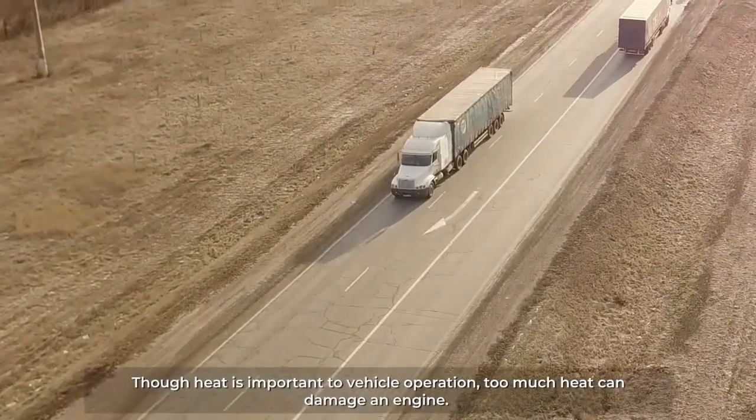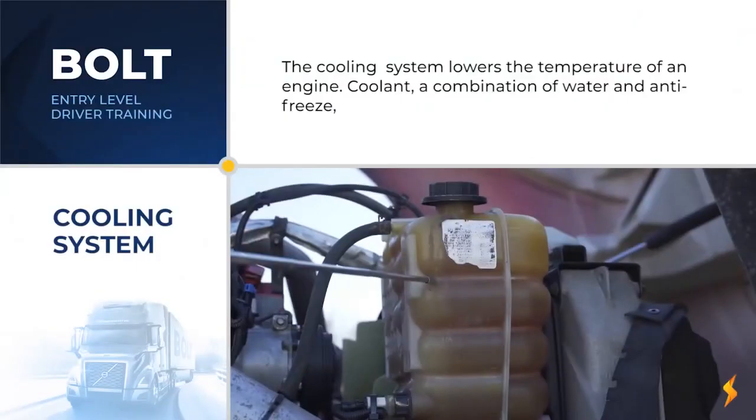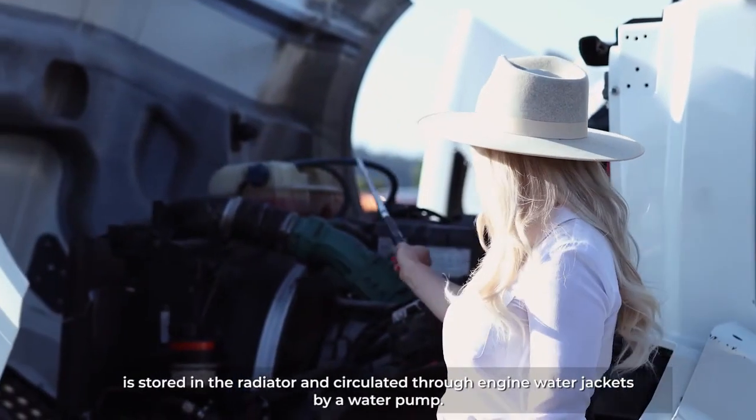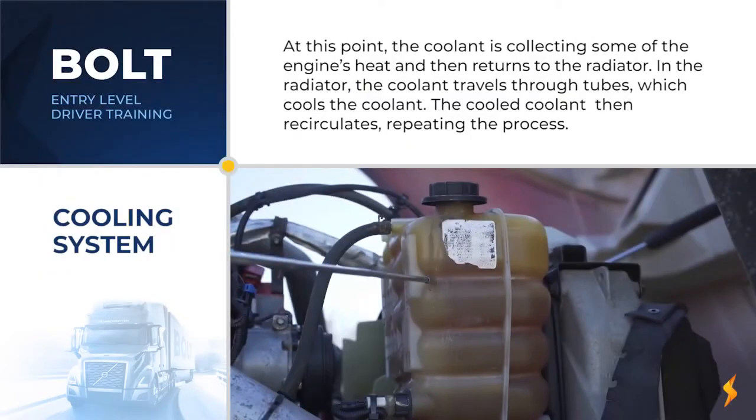Though heat is important to engine operation, too much heat can damage an engine. The cooling system lowers the heat level of an operating engine. Coolant, a combination of water and antifreeze, is stored in the radiator and circulated through engine water jackets by the water pump. At this point, the coolant is collecting some of the engine's heat and then returns to the radiator. In the radiator, the heated coolant travels through tubes which cool the coolant. The cooled coolant then recirculates, repeating the process.